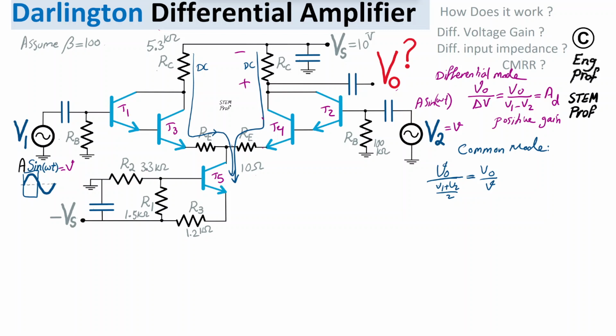As we are increasing the voltage V, in this example it is injecting an AC, because when we are increasing the voltage V, we are increasing the base voltage, which means we are injecting a current like this, a small signal AC, that is added on top of the blue DC current.